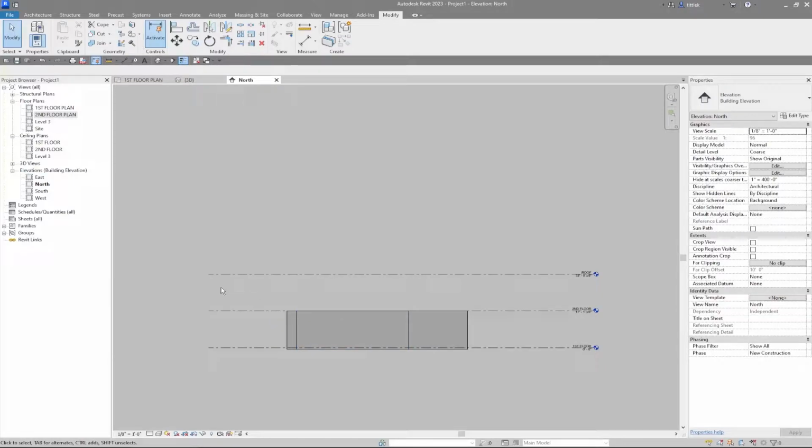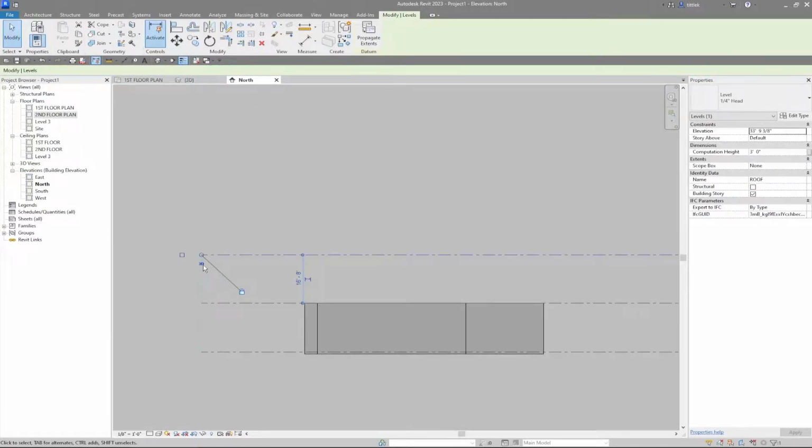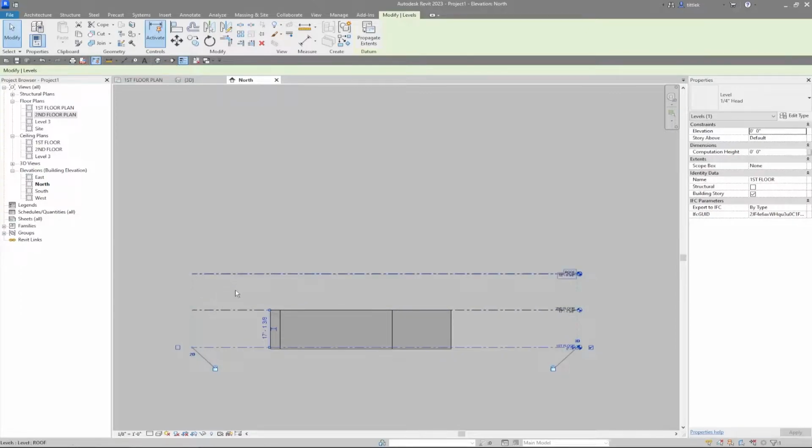This is a little tip I try to tell students: if I adjust these over here to be closer to the building so that it looks nicer, it's adjusting the text on the opposite elevation. So it's going to adjust the south elevation as well, because currently when you select these, they say 3D. I don't want that to happen. So what I'm going to do is select each of these and click 3D to make them 2D. And that essentially removes that parametric relationship from the other side of the drawing. So now I can pull these into a more comfortable spot.